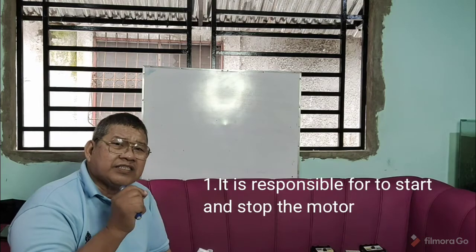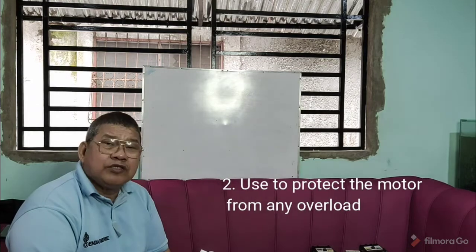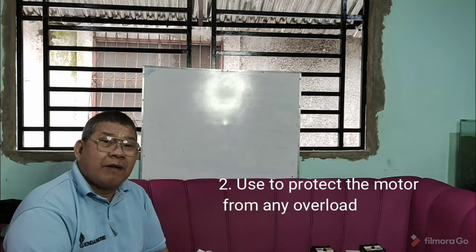Okay, first, this is responsible to start and stop the motor. If you want to start the motor, you just simply press the button, and if you want also to stop the motor, of course, you have to press the button, stop or off button. And at the same time, this is also used to protect the motor from any overload.